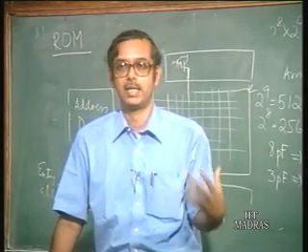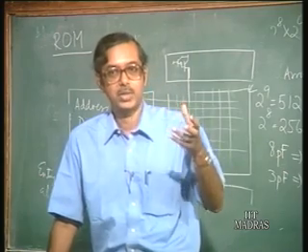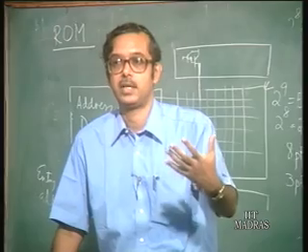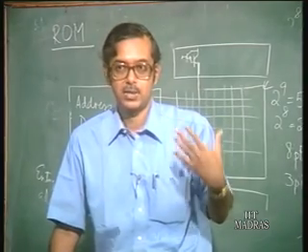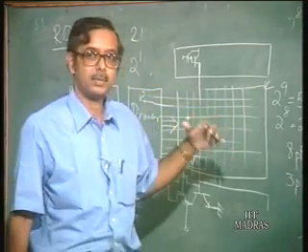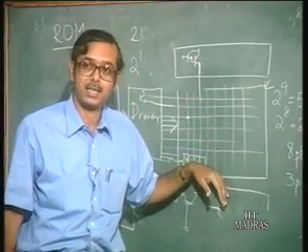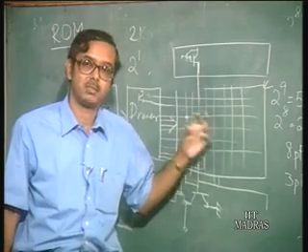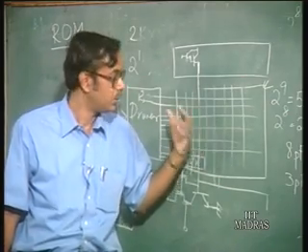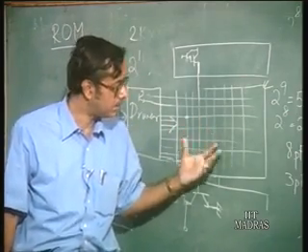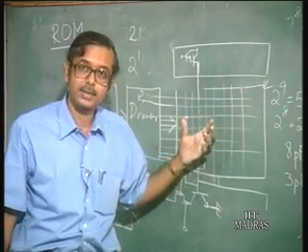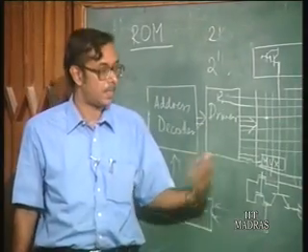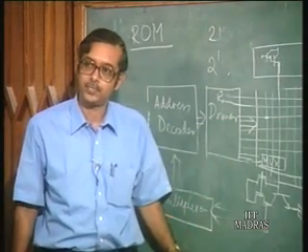Okay, so the transconductance is very low. So you actually require a small change in input voltage to make a large change in output current in a bipolar transistor. So that is the advantage. If the input line has a large capacitance, because the bipolar transistor's input voltage variation requirement is much smaller, the time required to change the input voltage is going to be much less. So that is the advantage.